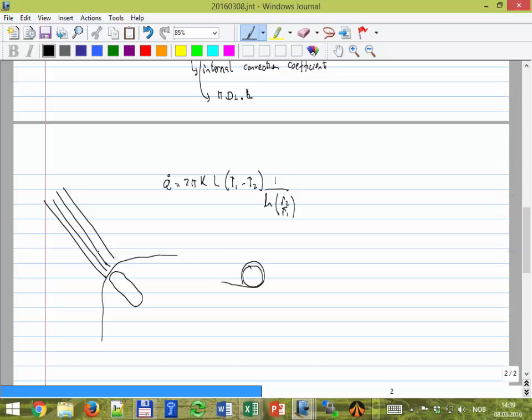What are the other layers? Insulation. Just the two layers. The inner layer is to stick to the pipe wall, and the outer is just for protection. And really what is doing the insulation is the white one that you see in the middle, because usually structurally that's not very strong. So if you leave that by itself, it might break, it might get detached from the pipe wall. So you put these two for protection and for the integrity of the inner layer.